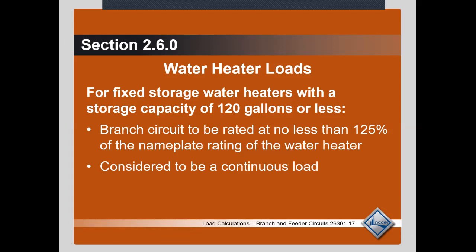I believe it. So we got water heater loads for fixed storage water heaters with storage capacity of 120 gallons or less. Branch circuit to be rated at no less than 125% of the nameplate rating of the water heater.